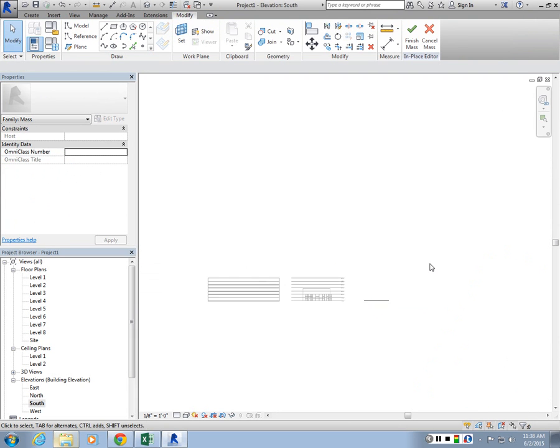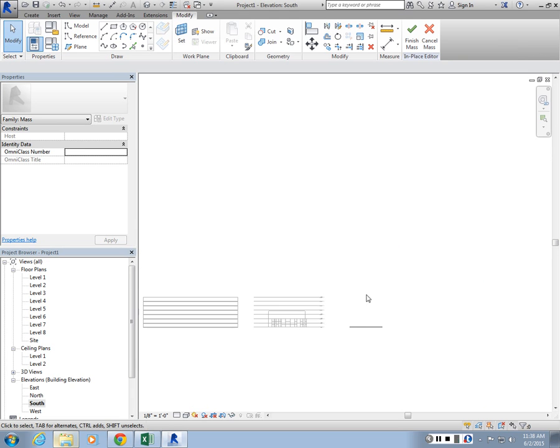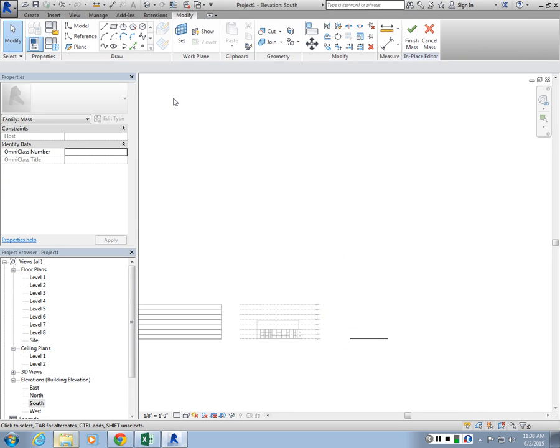Now you can actually set up work planes where you want to draw these profiles, and you can use them to input the profiles as well. So if you look up here, the massing tools are kind of a hybrid, right? It partially shows you the project and partially enables you to create family-based construction objects. So we could set up reference planes, for instance.